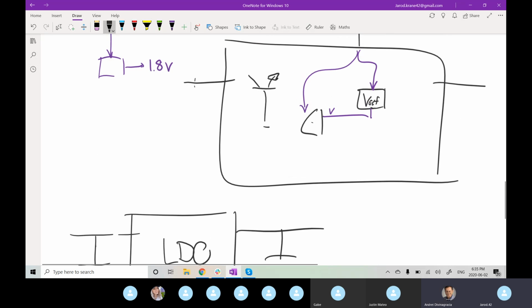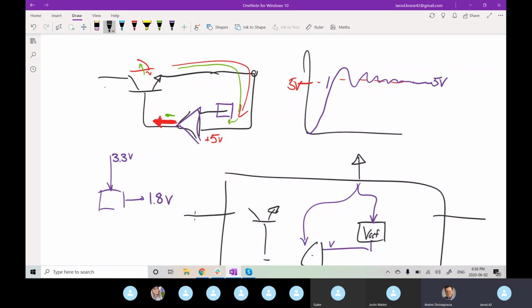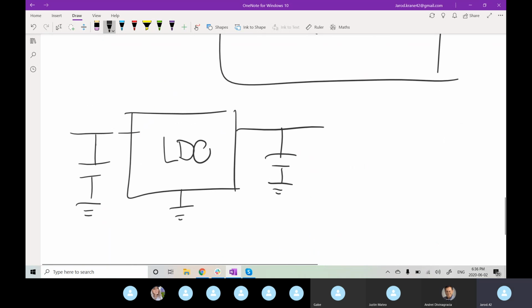It has the effect of smoothing these out. Any substantial spikes are going to be instantaneous, like a transient high frequency just for a quick second. Boom, it's all of a sudden up at 9 volts. That capacitor is able to kind of eat at that voltage, so we don't send 9 volts to our devices that may only be 5 volt tolerant.